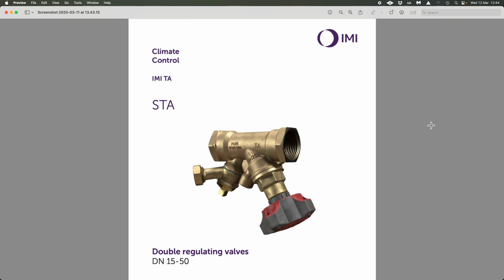So they've made two or three errors here. They have taken that cold water storage and they've capped it off, and they've teed into the drinking water circuits, which are not designed for large flow rates in big blocks of flats, and joined the combination boiler into those on the hot water side.